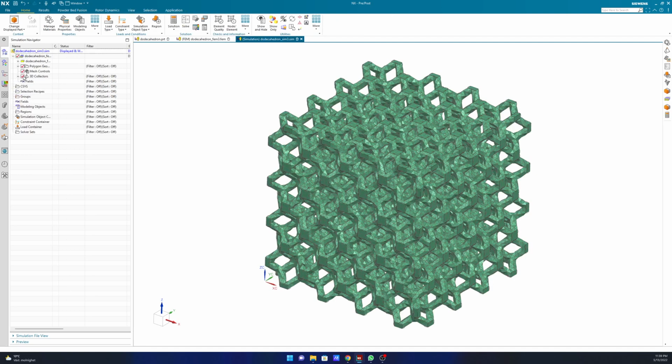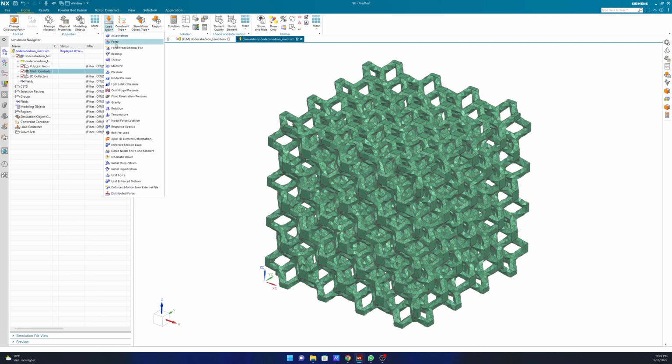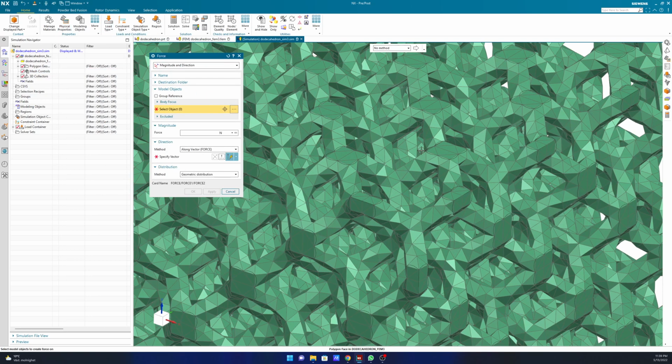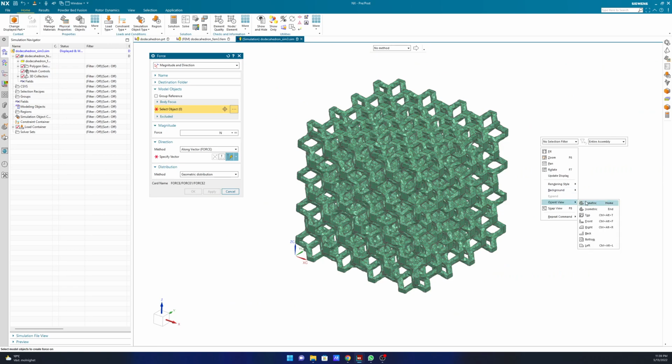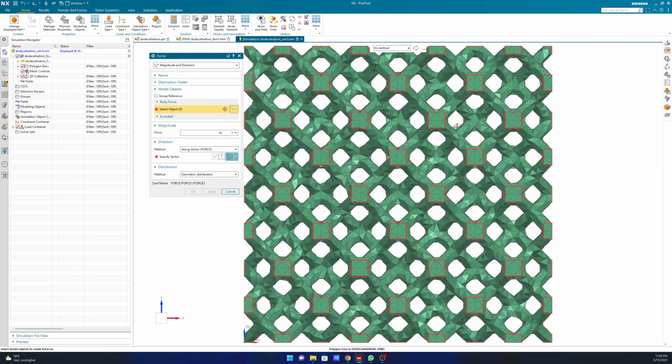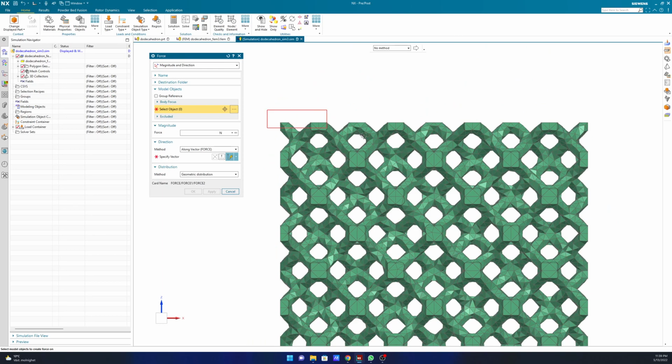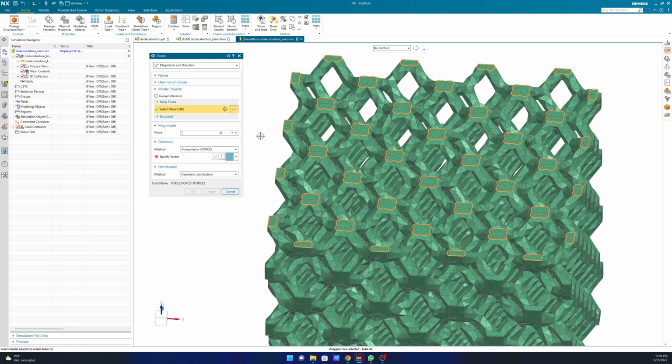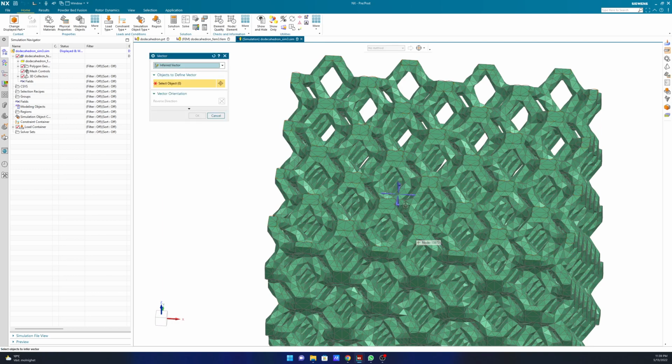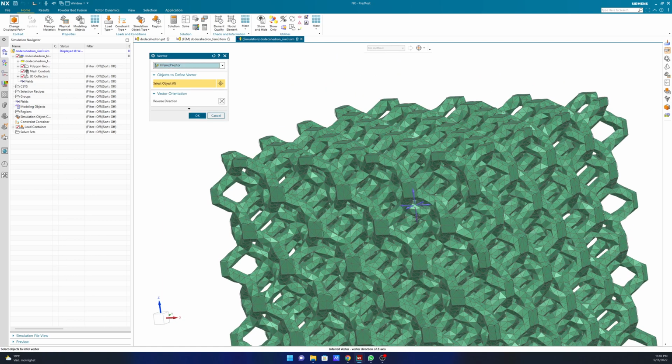If you can see here, the mesh controls, the mesh is connected here from the .fem file. It's connected over here. Then we'll start with applying the loads. Let's go by a Z direction load. Let's do it in the front view, move it, select the top faces like that. And let's say a load of 1000 newtons with a given direction downwards.